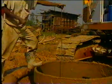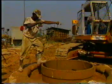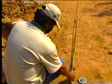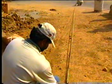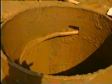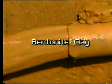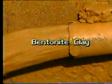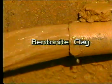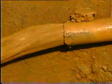The depth of the excavated borehole is measured with the help of a chain. The length of the chain is then measured with the tape and compared with the required depth of the borehole. If the depth of the borehole conforms to the designed depth, water mixed with bentonite clay is pumped into the borehole so as to prevent the caving in of the sides of the borehole.